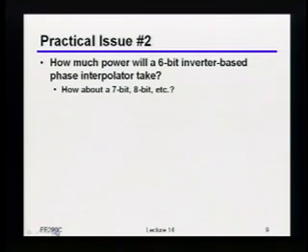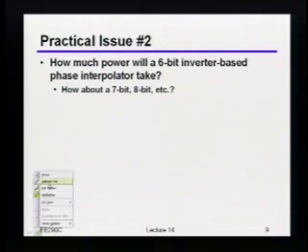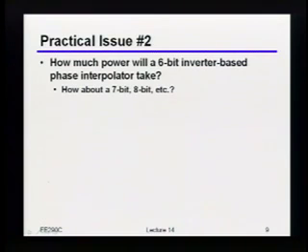How much power is that going to take? And by the way, I don't necessarily want a number, but I want the philosophical, or the underlying reasoning, behind how you'd get to the number. Well, whatever our 64 inverters switching at the full clock speed suck down? Yeah, exactly. So what you basically said is it's going to take whatever 64 inverters is. Now, it turns out it's not quite exactly that. It's 128, right? Okay, well, it's slightly more complicated. Let's actually draw it and you'll see, but you've got the right thinking.